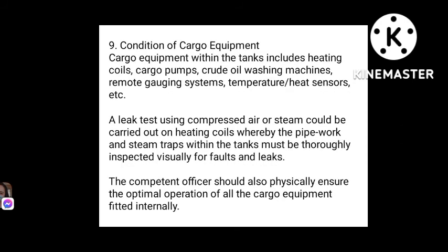So the last is the condition of the cargo equipment. Cargo equipment within the tanks includes heating coils, cargo pumps, crude oil washing machines, remote gauging systems, temperature or heat sensors, etc. A leak test using compressed air or steam could be carried out in heating coils whereby the pipe work and steam traps within the tanks must be thoroughly inspected visually for faults and leaks.